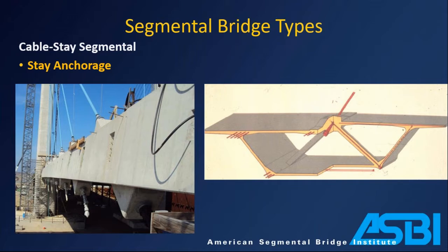You see a lot of anchorages along the edge. That's what you see over there on the left. So that's an edge girder type application. You would have that on both sides of the deck, running your way out. Just looks a lot like a typical blister, only difference being they're usually a whole lot bigger.